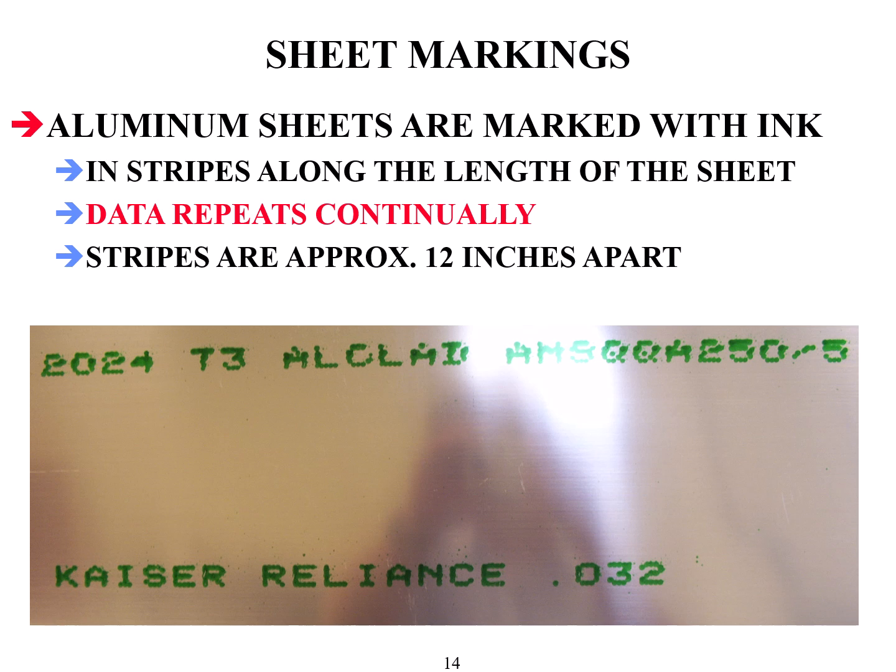They'll also put other data on the sheet just in case they have a problem. There's traceability back on that batch. That's that AMS and batch number information. It gives detailed information on that specific run of aluminum for traceability. But as you can see here in this picture, this is a sheet of 32 thousandths 2024 T3 clad material. It makes it very easy to identify when you go to a rack that's full of very different types of aluminum.